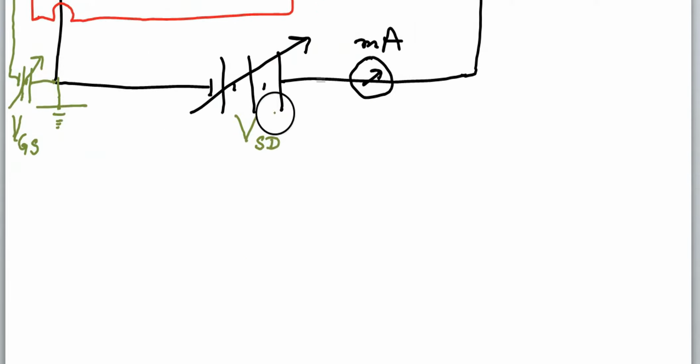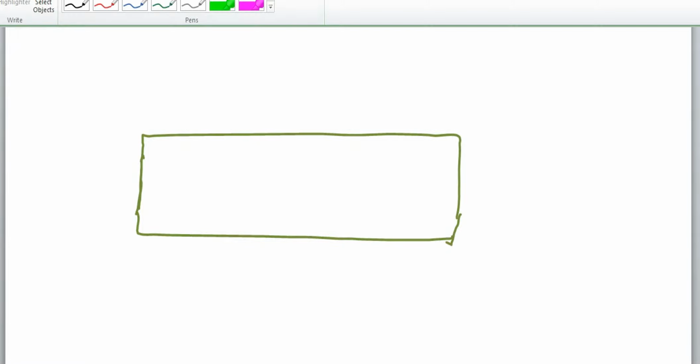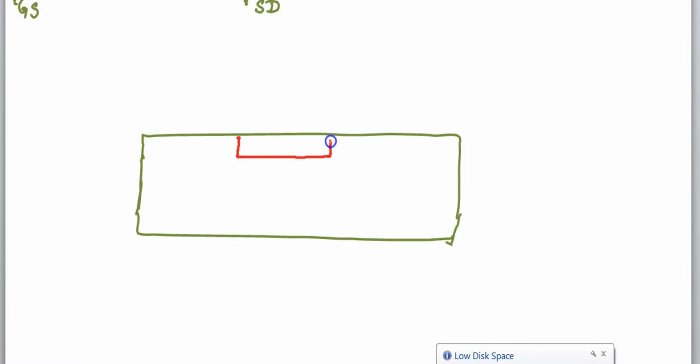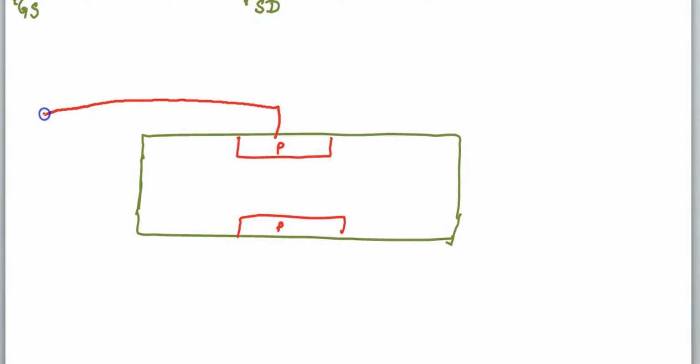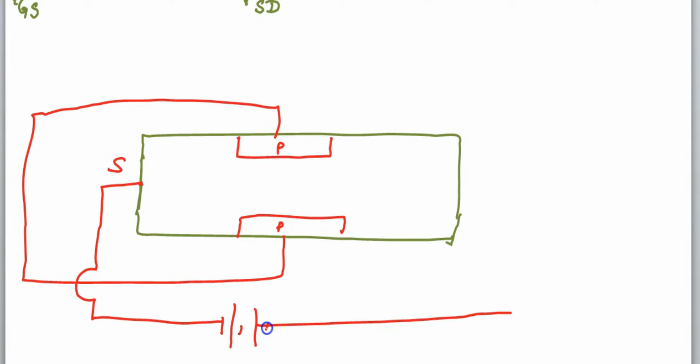Between the gate, the current, the electrons, have to pass, and the gate can be opened or closed by applying a gate potential. If the gate, because it is p-type, is given a negative voltage, the gate will close. The gate will close by giving a negative potential to the p-type gate.